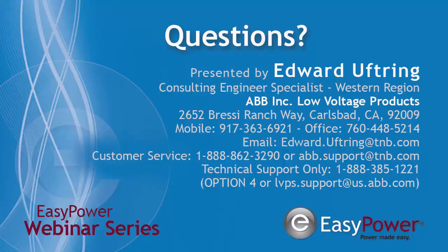Every time you turn that breaker on, those contacts, the bimetal, and all the electronics inside see a huge surge as they're trying to get the full current. Especially when you look at inductive loads and you're talking about a current that is 90 degrees out of phase with your voltage, it can cause some havoc on the internal components.